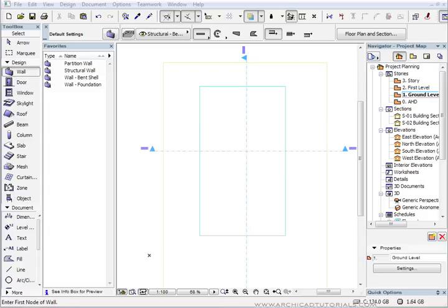So there's a couple of rules that I've come across which hopefully you can use. A couple of guidelines which maybe you could take on board is to model everything down to, say, a scale of 1 to 20. Anything under the scale of 1 to 20 you may as well do in 2D. Now there are some exceptions to that rule. The correct thing here to say is if anything appears more than once in a project, it should be modeled, because if you see it 2 or 3 times you probably get the benefits back from modeling it.